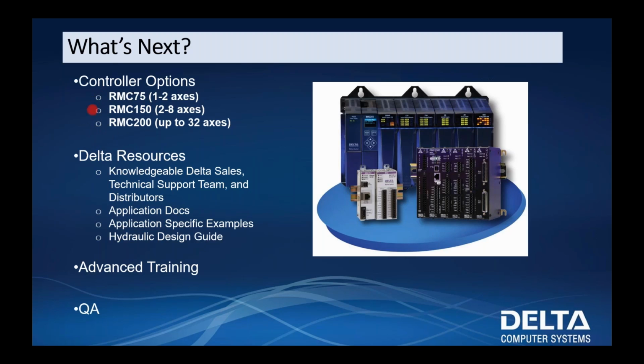So any of these examples you wanted to set up with these controllers, you'd be able to do it just fine, barring maybe the flying shear that used 3 axes, and we've only got 2 with this RMC 75. You could probably fit one in there, but you couldn't do it the exact same way.